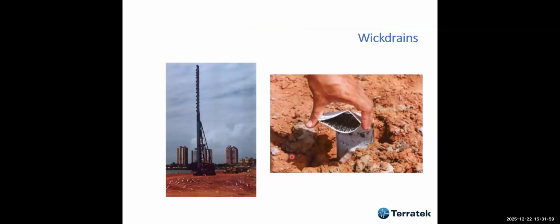And this was a very interesting project that we carried out in the 90s, I don't remember exactly when, in the north. It was the Hansen Lagoon. We did all around the lagoon. It was a big project, 6 kilometers of perimeter, and we used wick drains. These wick drains were much better because if they kink, they don't stop the water coming out. These were much better, as you see here, a mixture of plastic that doesn't allow it to kink and to stop the flow.